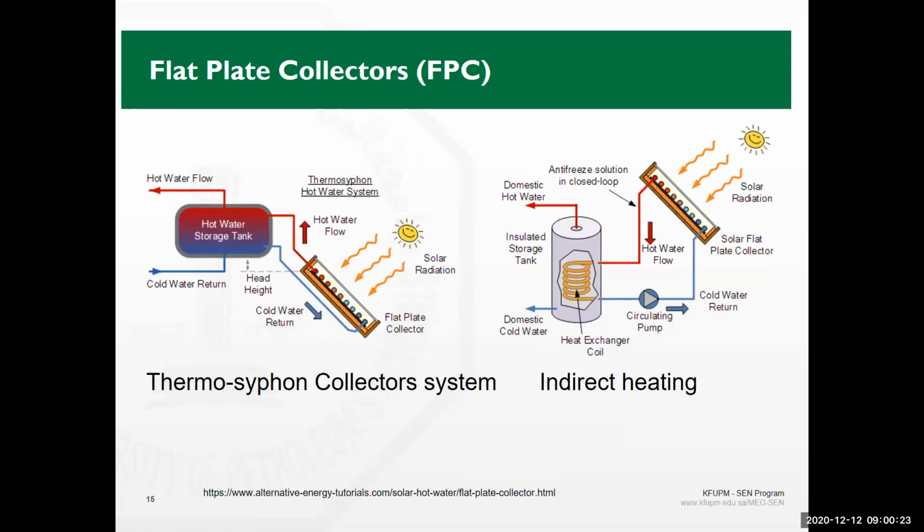Especially if you are interested in water heating, what we have here is some sort of indirect heating, which means that this heat exchanger, which is the hot water storage tank, basically has cold return from the load. The load could be, for example, an air handling unit in a house if you are looking for heating, or it could be direct utilization.